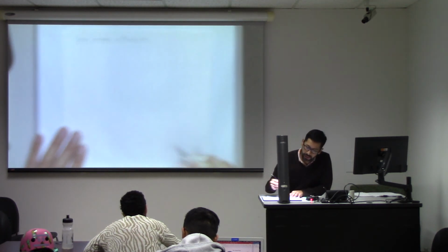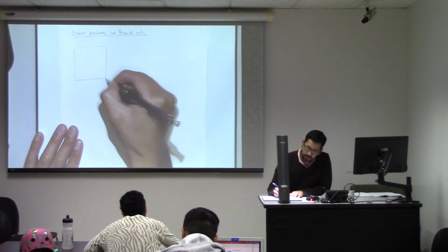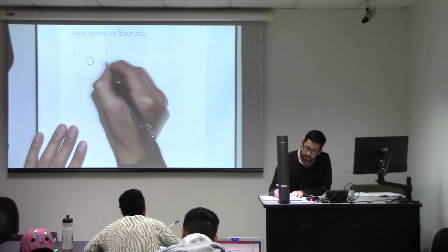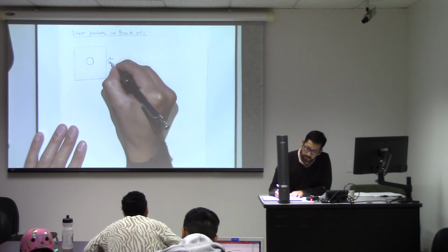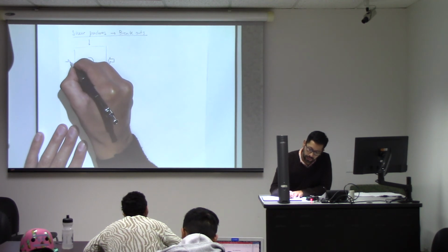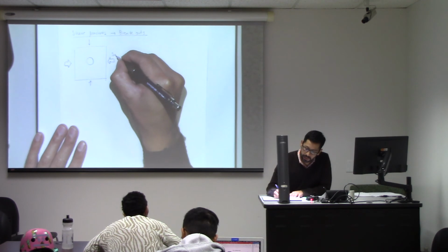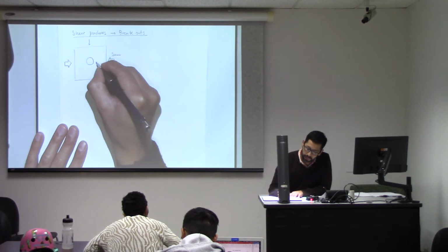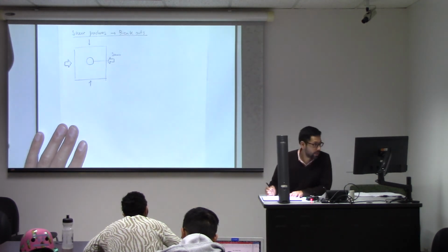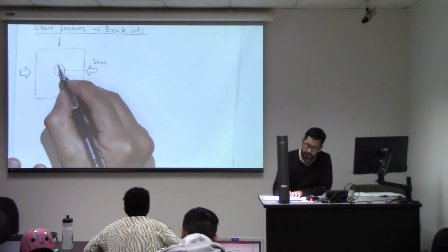And basically, in this case, similar to what we had before, if we had the maximum principal stress coming in this direction and the minimum principal stress coming in this direction, the maximum compression around the wellbore is going to be at these locations.